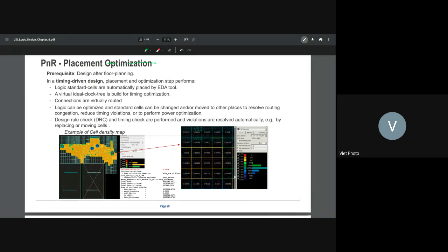For example, let's see like this. We have that here, go to another one, and then the clock goes like this, coming from the same source, right? So D here, and Q. Let's say we have a data path. I think the data is here. Now this one is the clock. So the clock is going to the first one and the second one, right? It won't be the same, because these two flops are at different places. Then when you have a clock, I think last time I already explained, the clock won't have the same delay, which is the delta here, and it's called clock skew.